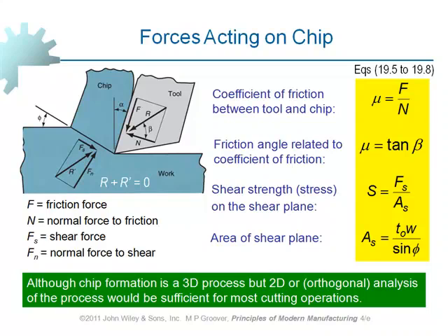The resultant force of cutting, which is R, is being applied by the cutting tool to the workpiece. And of course, on the basis of the third law of Newton, we know that for any action there is a reaction, which is equal and opposite in direction. Fine? This is what we know from Newton's third law. So, for this force R, which is the cutting force, there is a resultant force R prime, which is collinear. Sorry, in the opposite direction, and it is of the same magnitude.